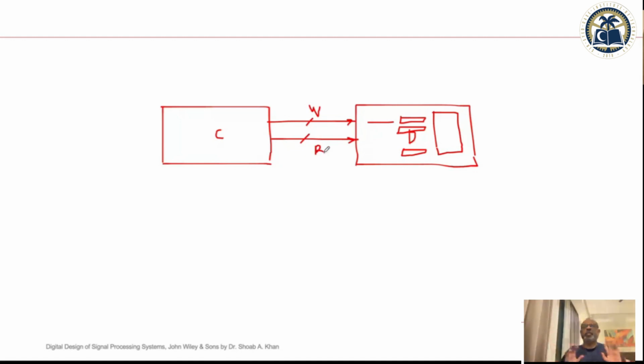Data path should only know, yes, I can write, yes, I can read. And it should send its status of the count so that the controller should know whether it is in an empty state or it is already full, and should generate all the status to anybody who is using it. Status signals are if it is underflow, overflow, and read write error. So three status signals. It should get a request to write, and it should get a request to read.